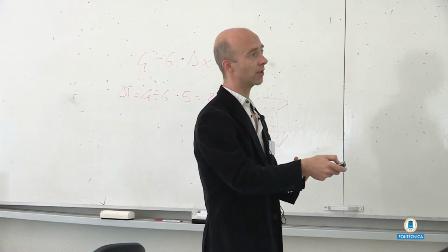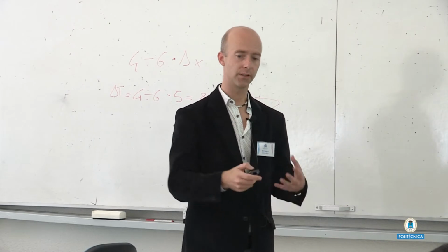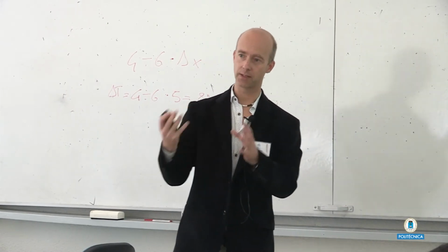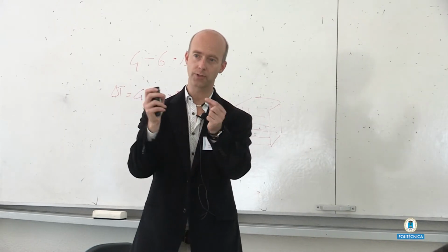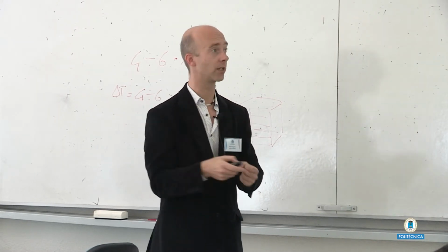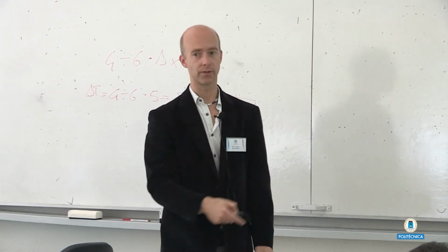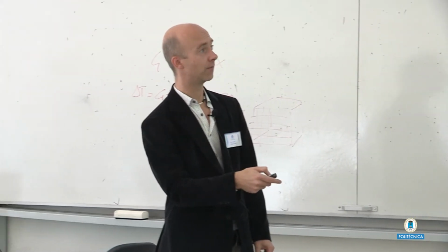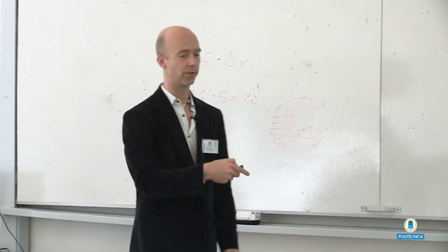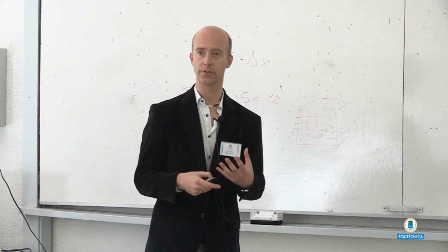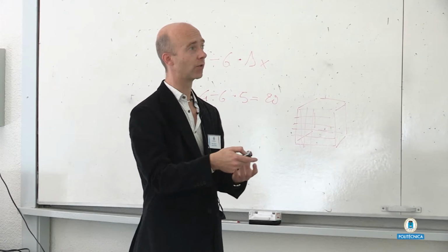You do the hydraulic computations on a coarse grid, something similar to what you do in a 1D model, where you use subgrid information, subgrid cross-sectional area, from a much higher resolution grid, and use slightly different approaches in what kind of information they use from the subgrid.